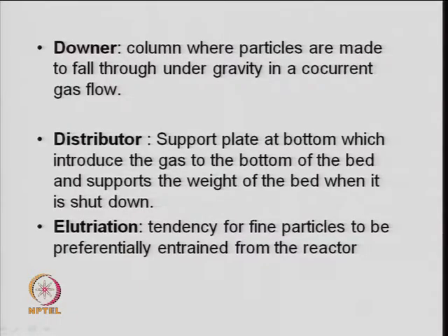Again, the distributor. I told you that there should be good contact, and that is to be identified through a hydrodynamic study. So, we need a good kind of distributor. The distributor is simply a support plate at the bottom, which introduces the gas to the bottom of the bed, so that a good kind of gas bubble comes, and it supports the weight of the bed when it is not in operation.